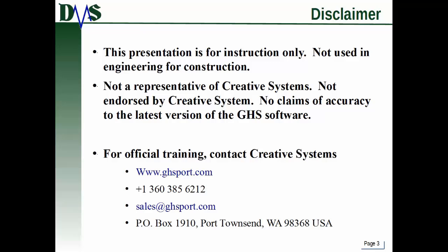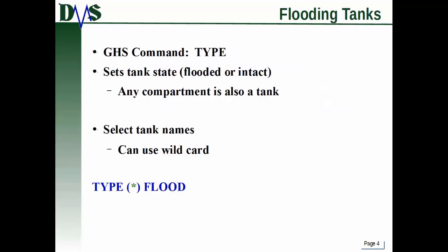So let's talk about how do you flood tanks. And remember that when we talk about tanks here, that can be a tank that actually carries liquid, or say just a compartment of air on the vessel. So you'll model all of your compartments as tanks as well. Now, you may not be filling them up with any fluid, and you can actually create a fluid of air, but you'll still need them to be tanks so that you can flood them.